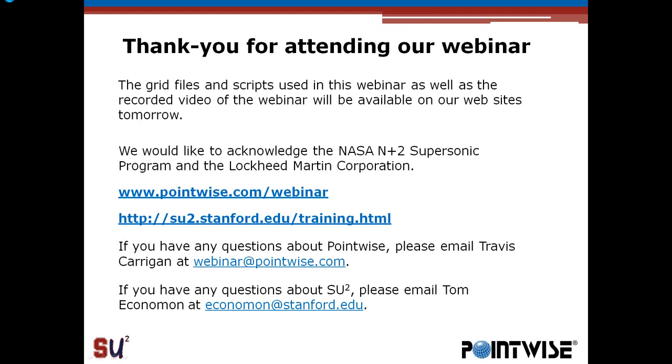CPU time for linear elasticity equations. In terms of specific CPU time, I can't give it to you. But in terms of the overall percentage of time for the optimization loop, which I think is more interesting, it's probably on the order of 5%. It's a relatively small amount of time for the full shape design loop. You're spending a lot more time computing the flow and the adjoints.